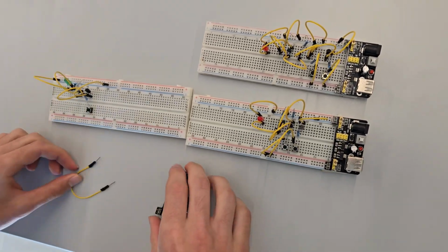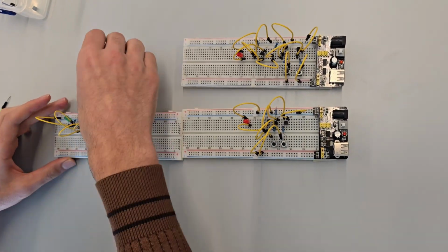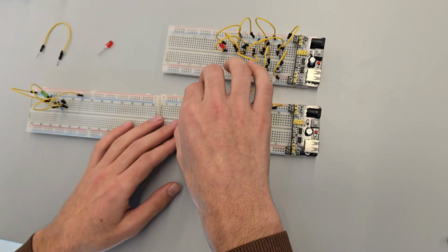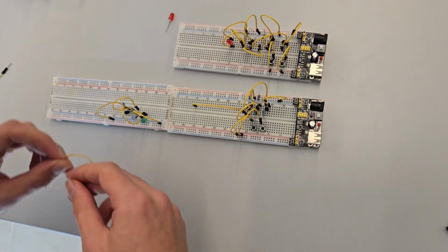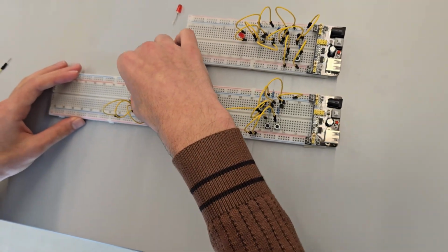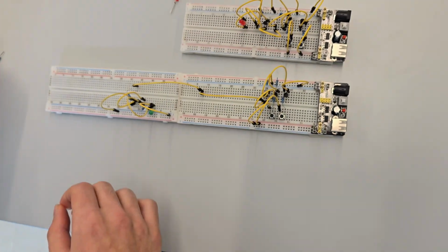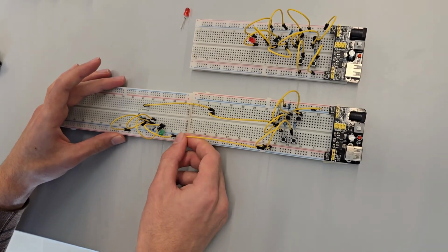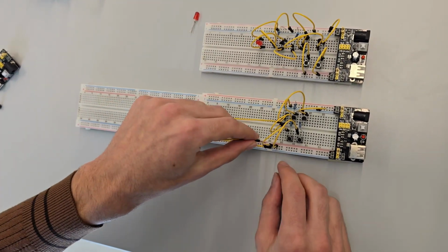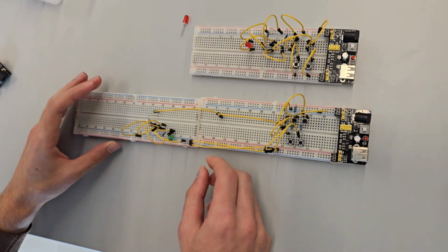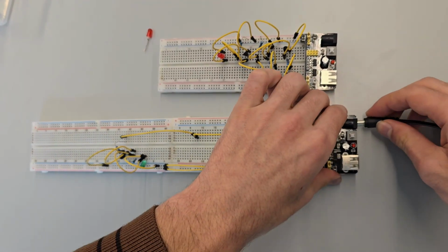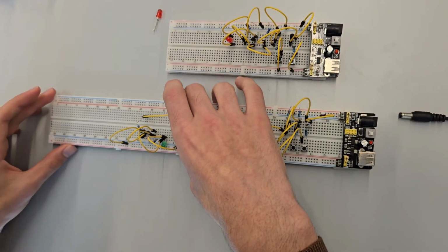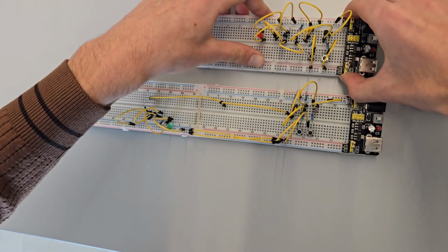First, we connect the AND gate and the NOT gate. We remove the power supply from the NOT gate and the lead from the AND gate. Then we connect the output of the AND gate to the input of the NOT gate. By doing this, we create a NAND gate. After connecting them, we test the circuit. It seems to be working correctly, so we can move on to the OR gate.